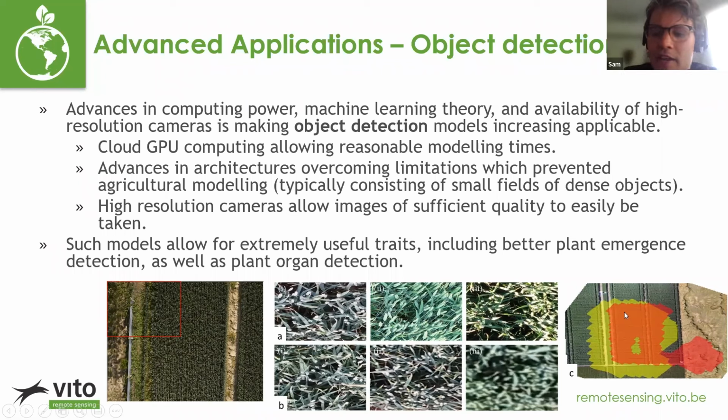When you are taking images of sufficient resolution with a Phantom 4 camera, the red boundary here indicates when you took images at the quality of B1, which is good for detecting objects, but because you weren't able to match features so well, you ended up not actually aligning images over the whole field.